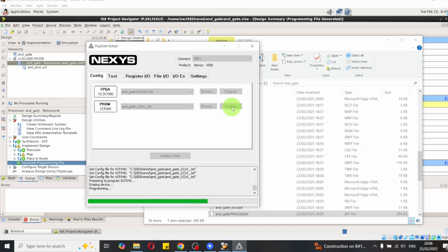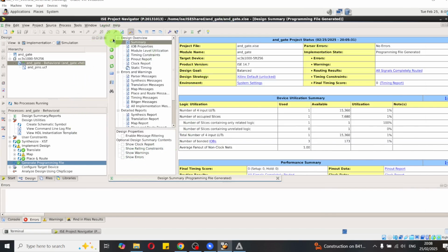If we power up, power down, it's just the thing that you need to remember, that on our board, the Nexys board, you need to change the settings of one of the configuration jumpers. This one has to be selected for flash, and then every power up, power down does not remove the contents of the PROM. It will be loaded every time.